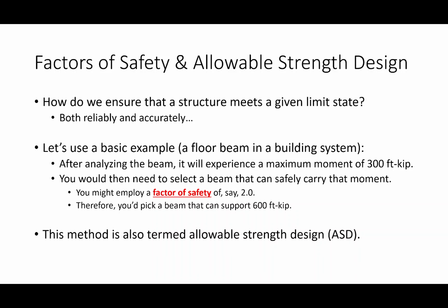Blanket factors of safety are still used. A good example is in geotech, where soil properties are so variable from place to place that it's more difficult to be scientific than that. Whereas in steel design, steel is a manufactured product, so you can be a little more scientific about it. Everybody get the idea there?